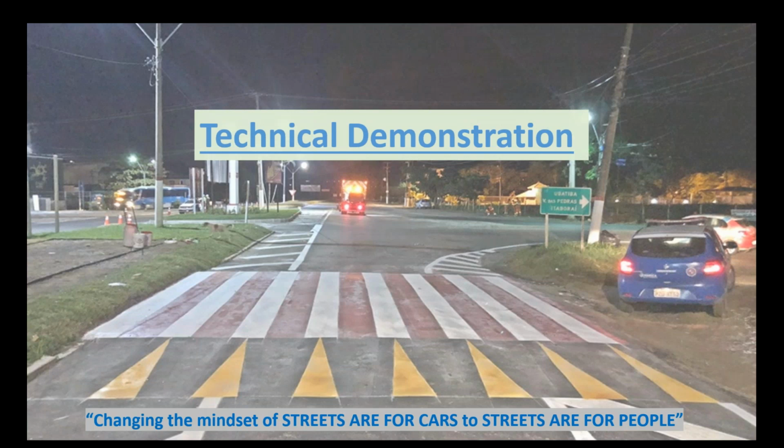Then we shall select the exclusion zones and lines, which are also known as non-drivable zones or the boundaries which the vehicle cannot pass through. Then the third step is to select the desired route for the vehicle path. Finally, picking the desired start and end positions of the vehicle within the route will let the software create the simulation automatically.